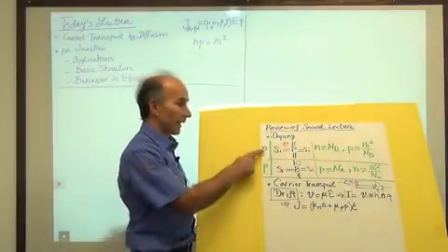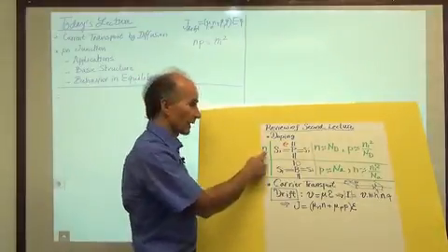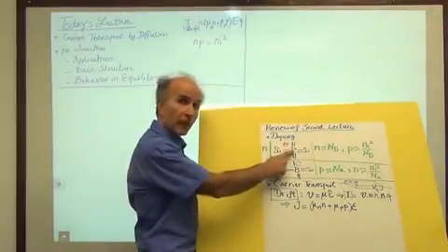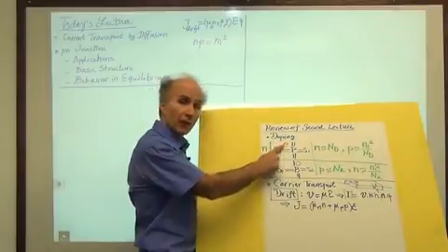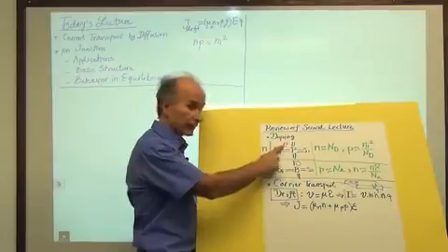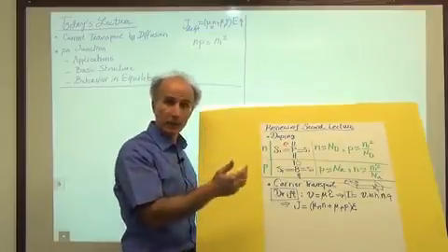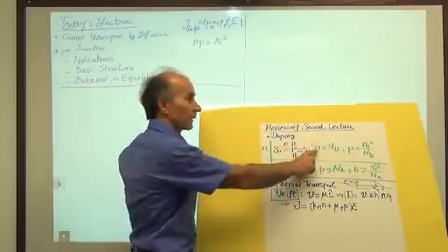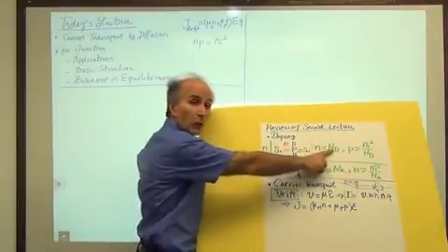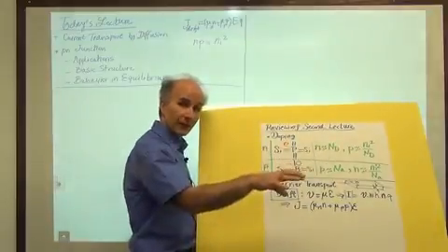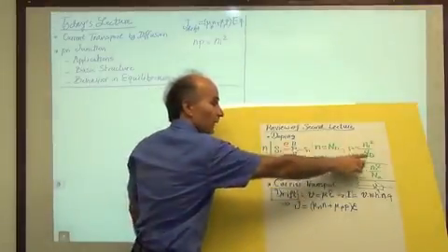So we said that in n-type semiconductors, we dope them with some sort of donor, for example, phosphorus. And because phosphorus has 5 electrons in its outermost shell, it ends up with one free electron that is capable of carrying a current. And if the doping level is high enough, let's say 10 to the 15 or 16, then the number of free electrons per cubic centimeter is approximately equal to the number of dopant atoms that have been introduced into silicon. And that means that the number of holes has fallen to Ni squared over Nd.